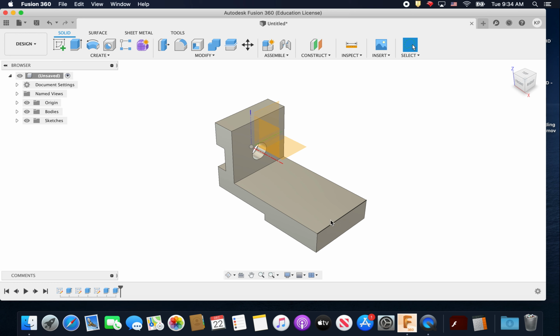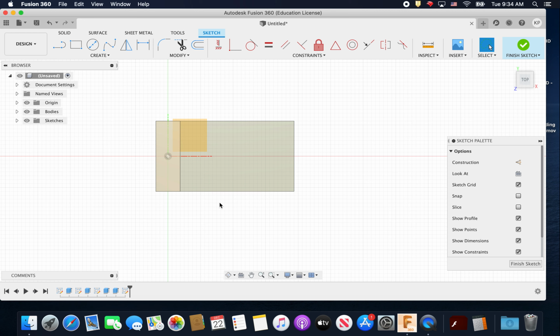We got one thing left. We have a little slot in the nose here. So we're going to use, got to remember to use my shortcuts, create sketch, select that surface, and we're going to use L for line. Make sure you're connected to the end here and draw your lines. Click and hold to get a circle.